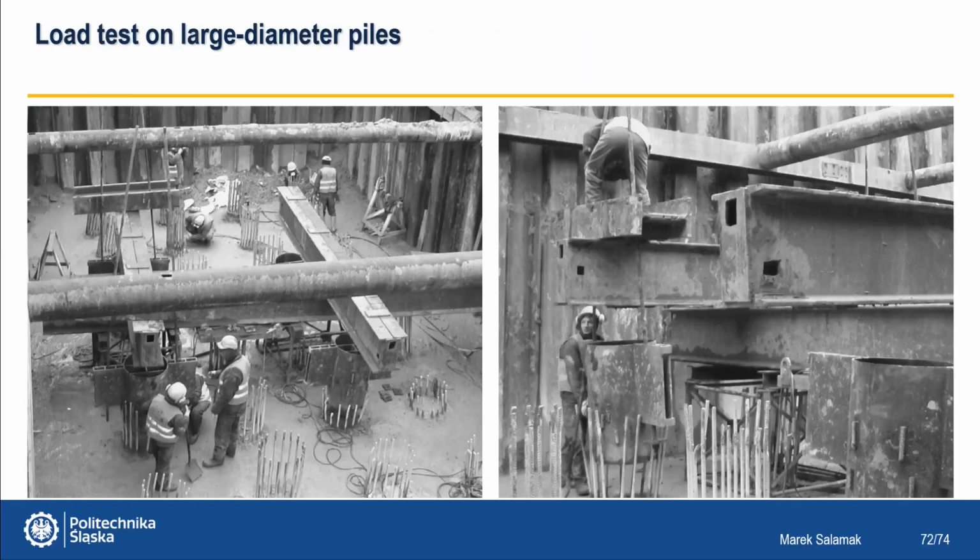The piles are subject to a trial load. A steel frame railing structure is attached to the exposed reinforcement. The piles are pressed into the ground by means of actuators pressed against the frame, checking the bearing capacity.